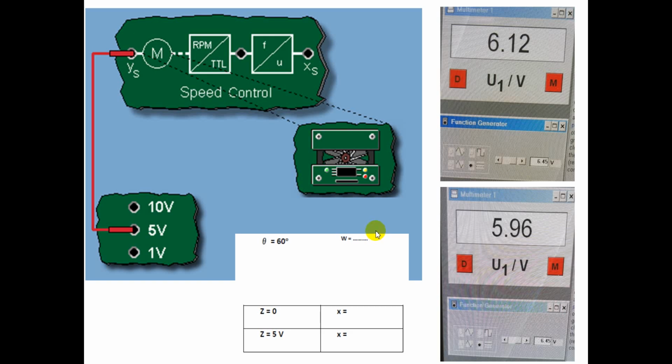Now the next step is, again we will introduce the disturbance. By keeping the same control circuit, we are going to connect it with the 5 volt here. When we connect the 5 volt, the motor or the fan will start running. We will wait to see how much our initial value, which we already adjusted, decreases.